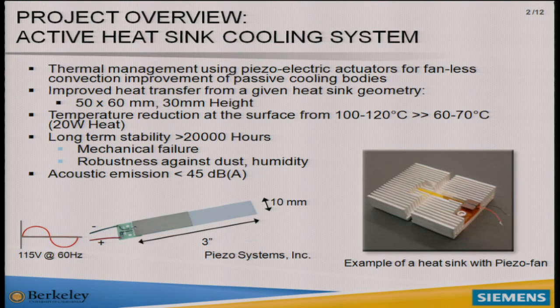Now, we've been told that there's about 20 watts of heat from an LED that we're trying to cool, and we're trying to reduce the surface temperature on the back of the system from about 100 degrees down to about 60 or 70 degrees. The other requirements are long-term stability, so more than 20,000 hours without mechanical failure, and very low noise.